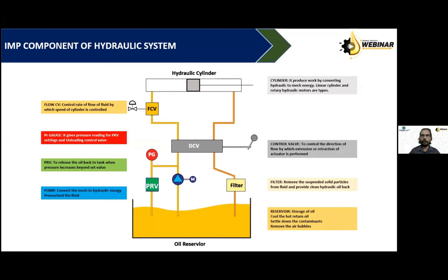These direction control valves can be controlled manually or with magnetic coils, or sometimes spring loaded with a single coil. So the external mechanism may be different. Internally, every DCV will remain the same: one spool and one body.